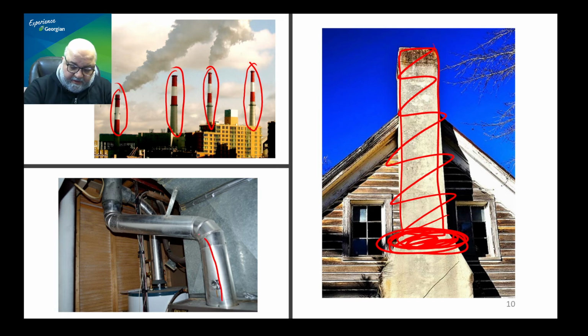In the third picture here, you have your two vent connectors, and then you have your main vent, right? A vent connector is basically that piece that connects the appliance to the main vent. This is the main vent going to the roof. Well, in this case, the application is pretty simple. I'm not going to dump the combustion products in the house. As simple as that. That's why I'm trying to find a way to build something like a pipe that will take my combustion products from my appliances indoors to the outdoors, right?